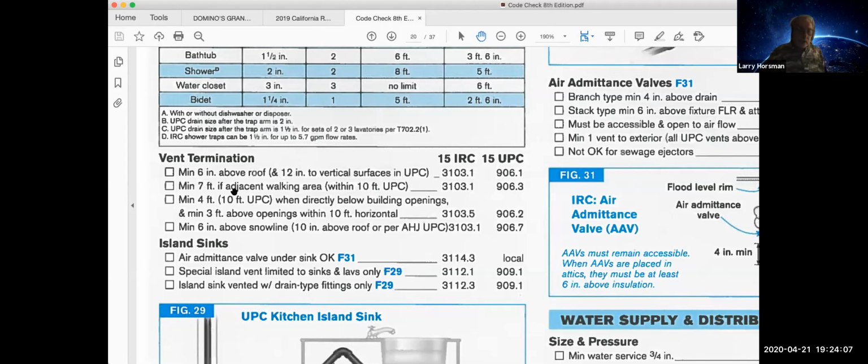The other is those gases in the sewer, as I said, are nasty. They can be corrosive. The concrete gets eaten. The hydrogen sulfide mixes with water and you get sulfuric acid condensing in the sewer. So normally what happens is they'll paint or coat the crown of the sewer, which is the top half, because sewer normally is not running full.